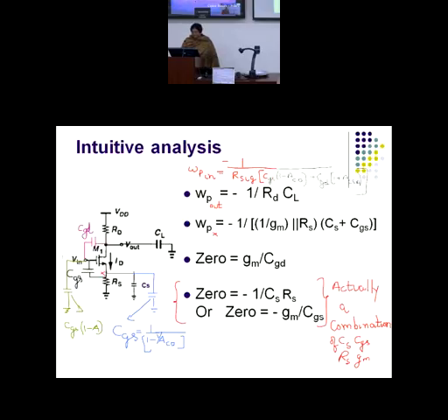It would be CGS multiplied by 1 minus 1 by A common drain. Not getting or not getting? What is the value of this component which is appearing when you break the CGS? CGS will be broken up according to Miller's theorem. So it would be CGS multiplied by, okay? It would be multiplied by 1 minus 1 upon the A common drain amplifier.